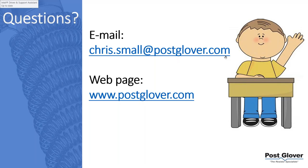Okay. There are some things that you have to worry about with UPS. To be honest, I would say UPS is probably the most tedious piece of equipment to use with the HRG for a couple of different reasons. Number one, a lot of times the controls on the UPS need to be solidly grounded in order to operate correctly. I shouldn't say a lot of times. A lot of UPS systems have it that way. So there's a problem. There's a conflict right there.